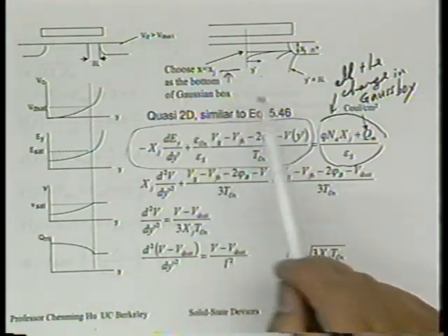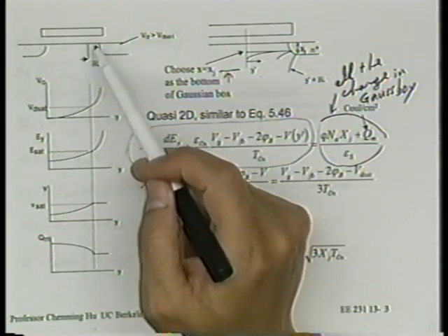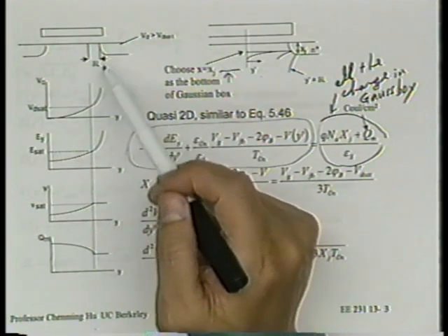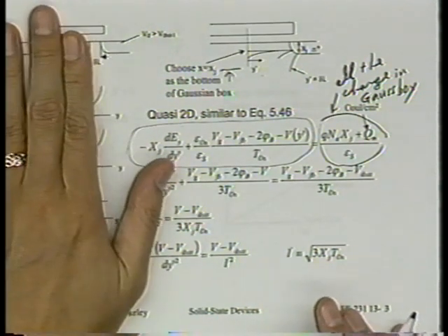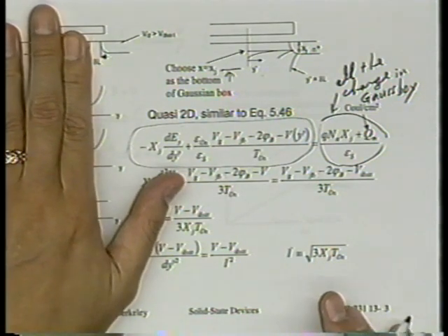Okay? Now here we're drawing you a different such line, and let me tell you what it is. First, remember, we're not looking for this line to go all the way from source to drain. Why? Because we're only trying to analyze this problem in a short distance from the drain. Do you see what I'm talking about? We're trying to analyze channel length modulation, and this probably only exists in a short distance within the drain.